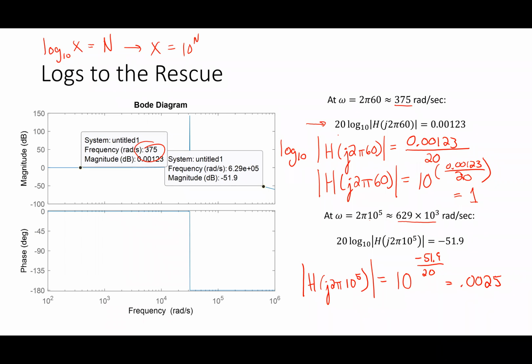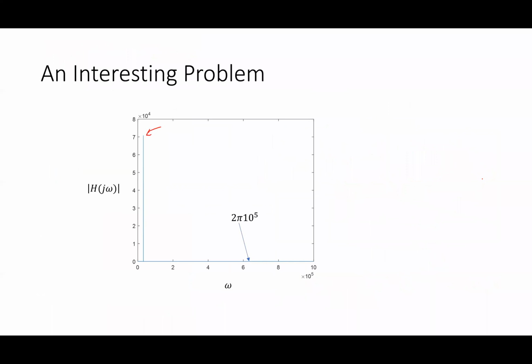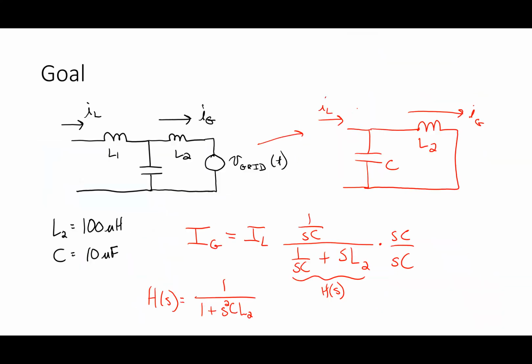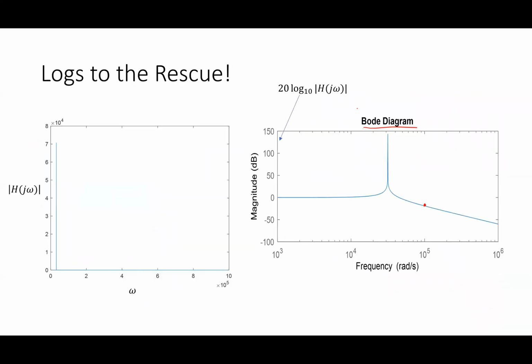Yes. So at 60 hertz, I multiply the input amplitude by the transfer function, and in this case, I think the 60 hertz component was 2 amps peak. So the output would be 2 amps peak, right? But the noise, which is 1 amp peak to peak on top of it, is going to become 2.5 milliamps. It becomes much smaller. All right, so that's our basic idea.